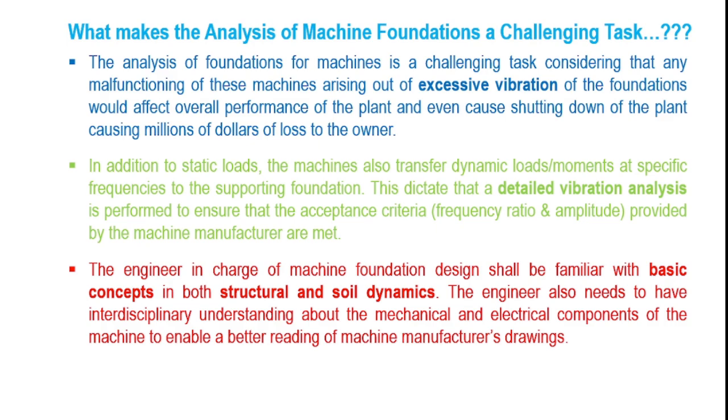Maybe there are thousands of information inputs, and say 80% of it is not required for your end. So the engineer must be able to pick up the correct input directly from the machine manufacturer's drawings, and in case any important data is missing, it is the responsibility of the design engineers to write to the machine manufacturer and get the required input before proceeding to the other part of the design.